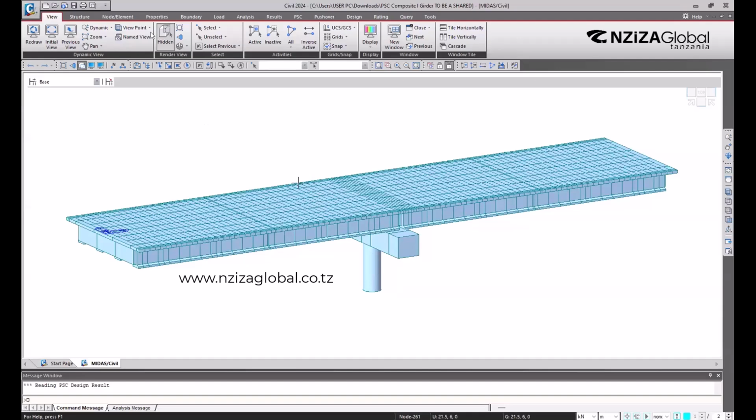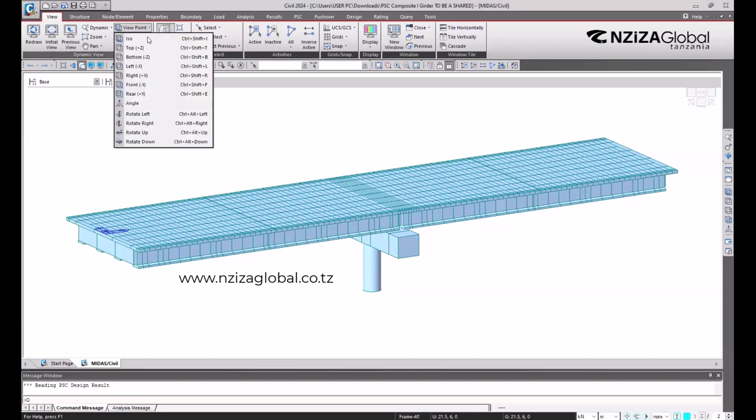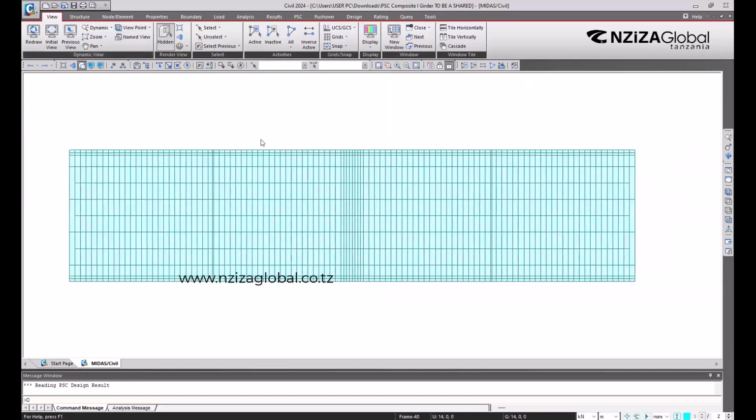Okay. I was saying that if I want to see like perspectives, I can use this ISO and see this view. If I want to use the keys, maybe I don't want to go through these tools, I can use shortcuts. You see, I can click Control Shift then I, which stands for ISO. If I want to see top, positive Z, Control Shift T, which stands for top. If I do that, you can see the result.